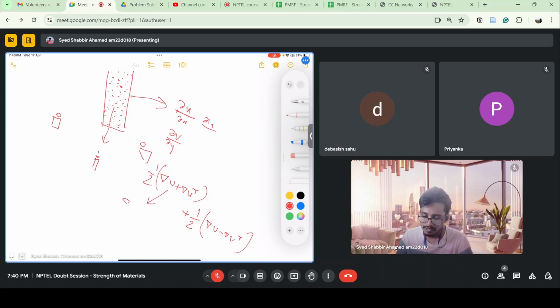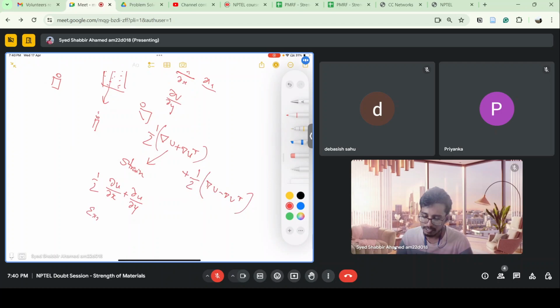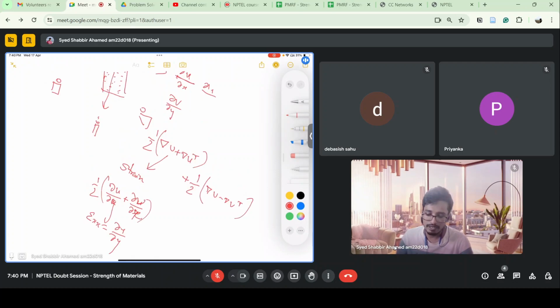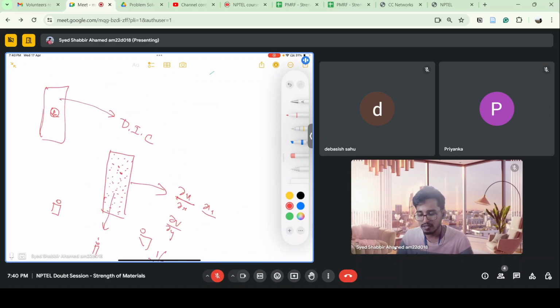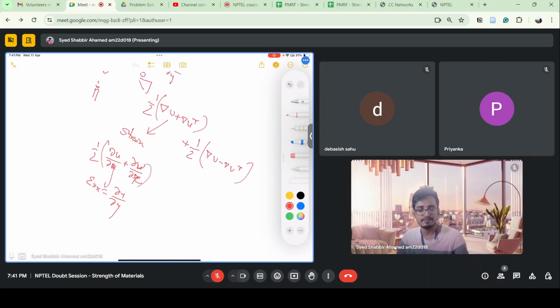So this is my strain tensor. That's why we get ∂u/∂x plus ∂u/∂x, times 1/2, so I'll get ∂u/∂x. So epsilon x is simply ∂u/∂x. If I have x and y, I'll get y here and x here, something like this. So u and v, the displacements. If I have the displacement gradient, I can get the strains from this. For every point on this specimen, I can get the strains using digital image correlation. So that is one technique to measure my strains.